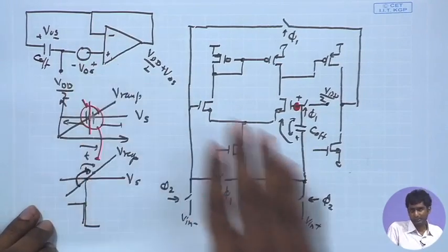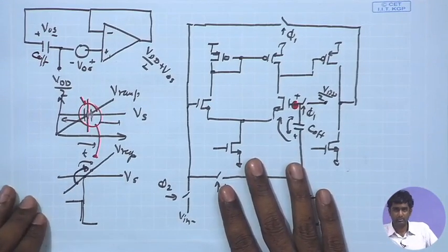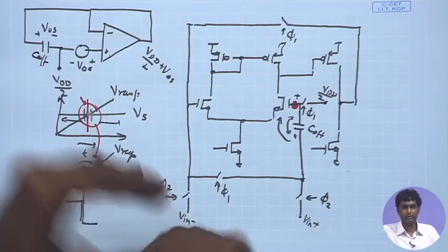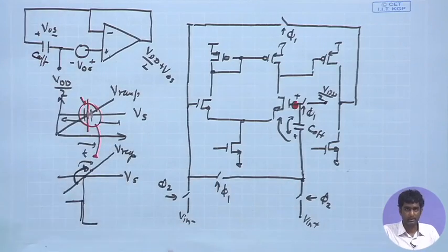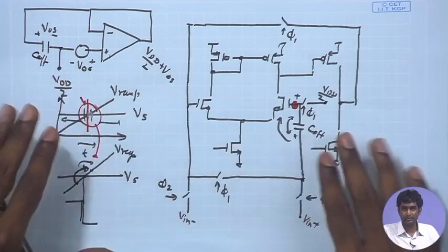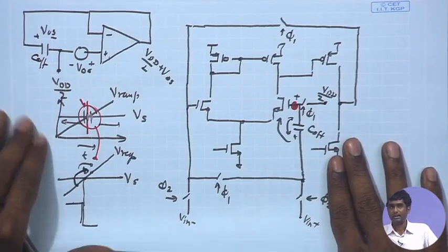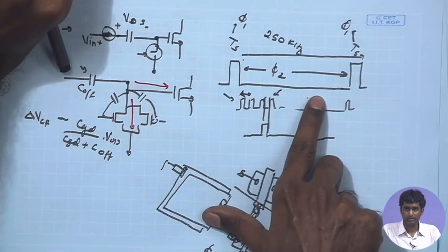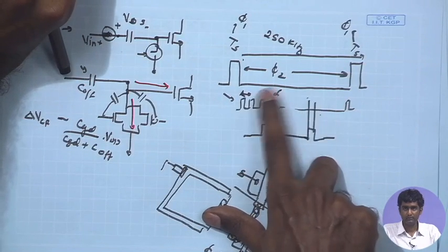In our design example, the comparator speed is not so critical because we are still dealing with 7-bit resolution. But if you go for larger and larger resolution, where 8-bit, 10-bit, 12-bit come in, then we can imagine what the speed requirement for the comparator is going to be. And in that case, can we afford to keep our comparator slower than the clock pulse? You can think about it, we can discuss this point later.